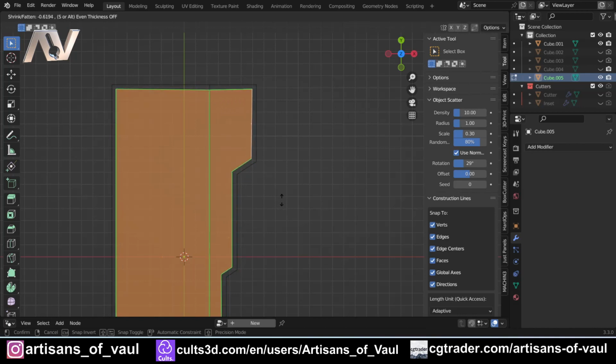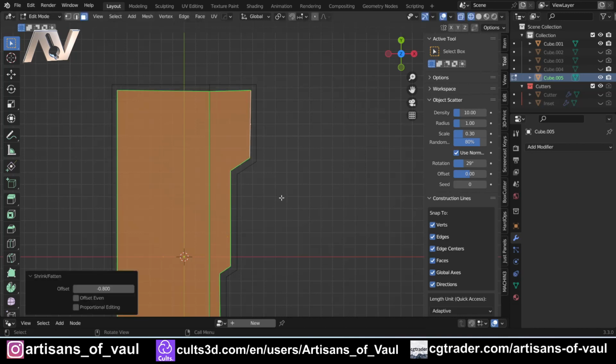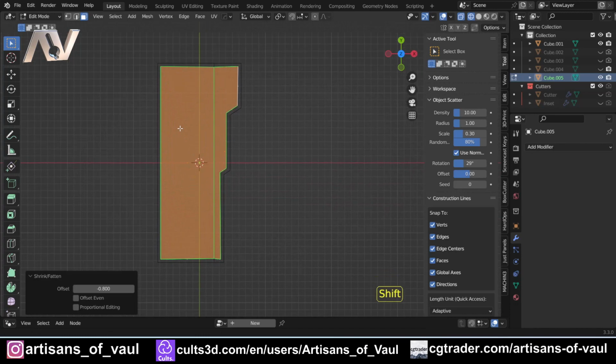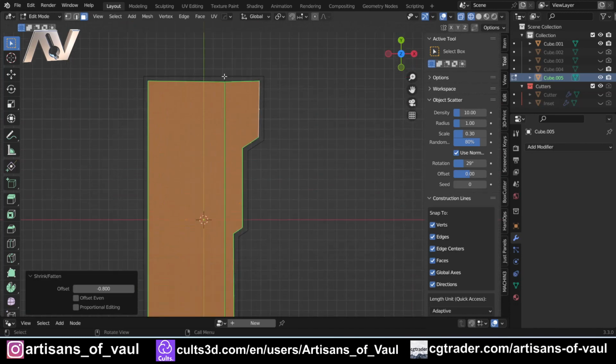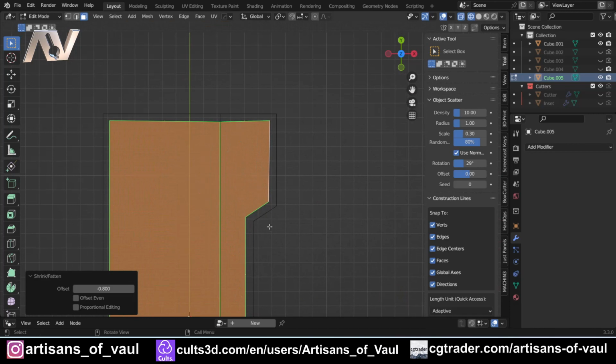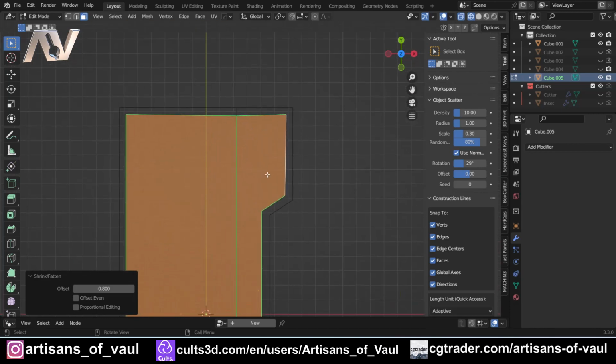For example, if I want it to be, let's say, I don't know, 0.8 millimeters, I could type minus 0.8, and we've got that being perfectly minus 0.8 on these axes. Again, with some slight errors where you've got these cuts there because it's getting confused by the normal direction. But we're not going to cut there, we're going to cut here, and again, we can solve that.